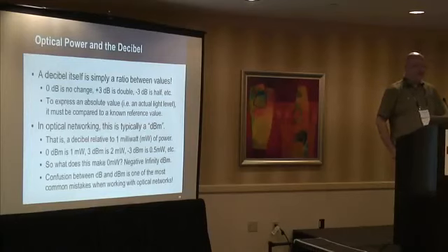But it's actually very common for people to confuse dB and dBm, especially if they're out there working with a light meter. They'll put it in a relative mode that's designed to look at testing off a test set somewhere, and they'll get a completely wrong value. So you have to understand there's two ways to measure it. One is an actual value relative to something, so you can say there's this much light, and one is this much change of light, so loss over distance, things like that.